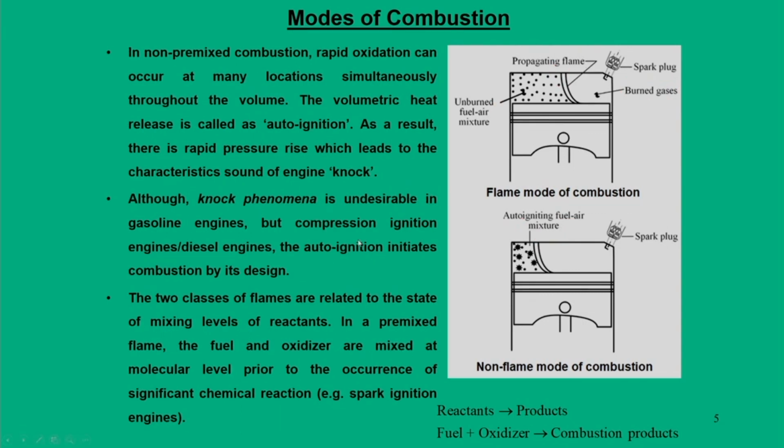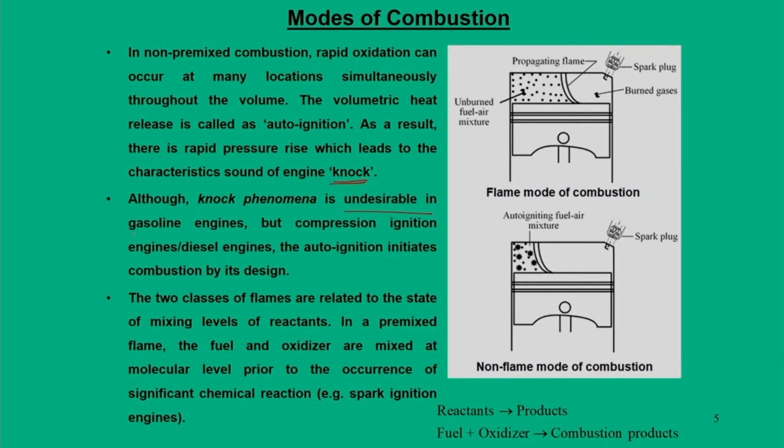Moving further, with respect to knocking. Knocking is a very common phenomenon that leads to a sudden rise in the pressure in the engine cylinder due to the chemical reactions. And in fact, we all know that this knocking is undesirable in diesel engines, but we cannot avoid this knocking in compression ignition engines, because the auto ignition itself creates a sudden rise in the pressure in the engine cylinders.